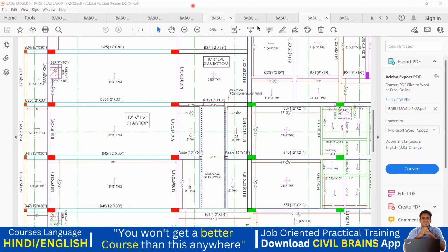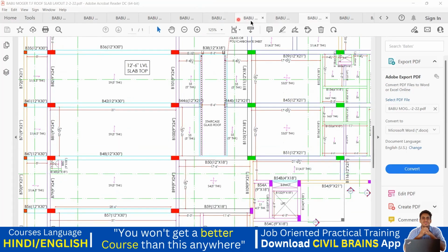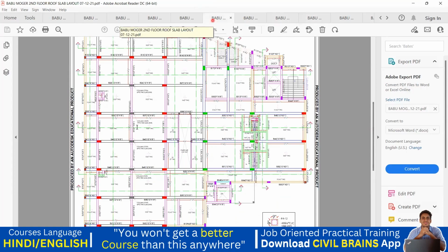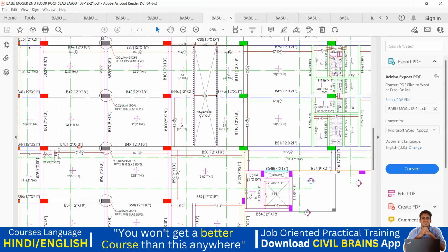That is why if I go back to your second, you see the size, it's 12-inch, breadth remains the same. Look at the depth, it is 30-inch here, right? Similarly, this is also 30 inches. Whereas in the second floor, what used to happen? In the second floor, you see the depth. It was actually how much? 12-inch by 18-inch, 12-inch by 18-inch. Now you have removed the column.